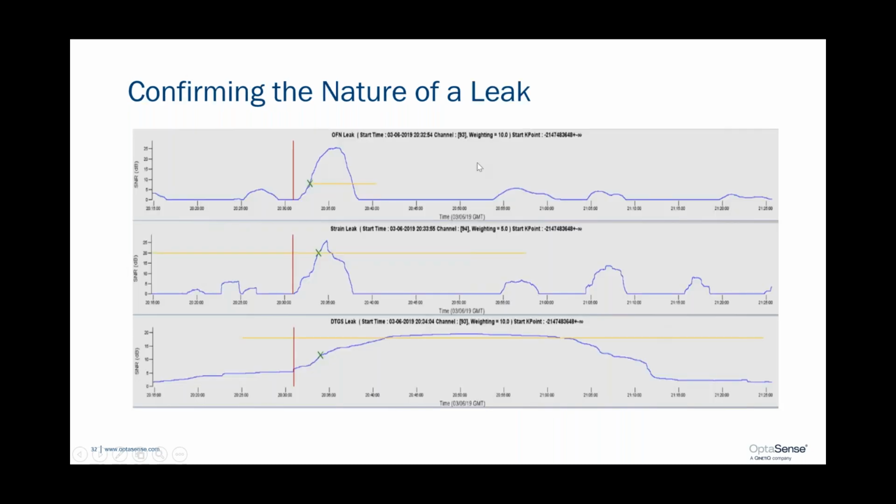All of these we can display graphically. The negative pressure pulse I've not shown because that's just instantaneous: is it there or is it not? But it's indicated by this red line where the leak was initially recognized by the negative pressure pulse. With each of the three things, we see first the orifice noise at a low level, and then suddenly, as soon as the leak starts, it starts building and rising, and then we reach the end. And there, the green cross illustrates the alarm from the orifice noise appearing later than the alarm from the negative